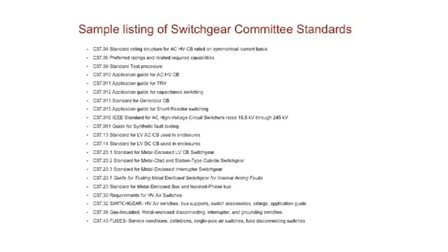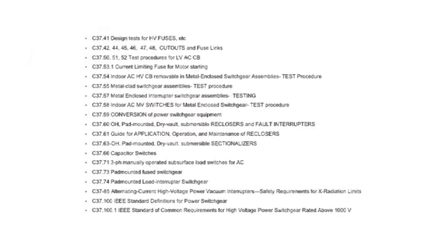There are even some very specific standards. Let's see if I had one here. Oh, that's an interesting one. C37.85, for example. There's a standard that requires some safety checks on vacuum interrupters, because vacuum interrupters can potentially, under test, emit X radiation. So if I work with vacuum interrupters, particularly in the testing part, you better at least be aware of the X-ray limits for these kind of devices.